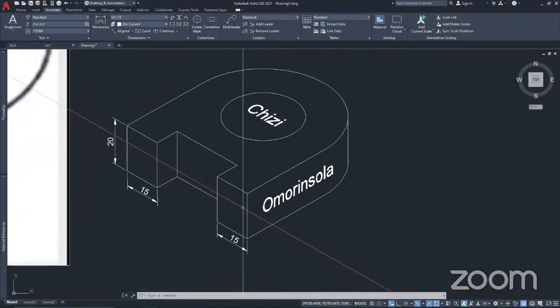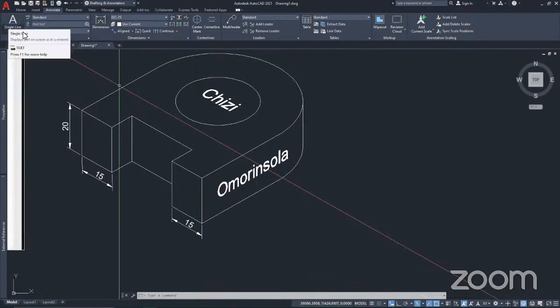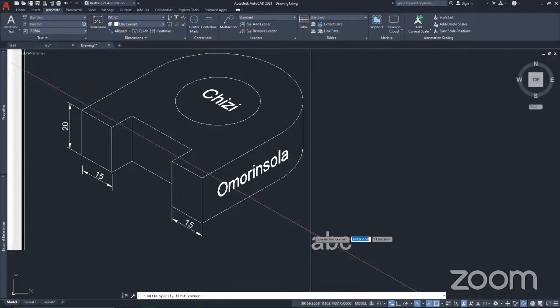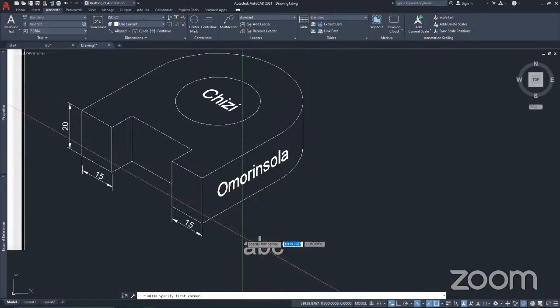Now I want to talk about the multi-line text. Drop this down, go to the multi-line text, and you want to do a multi-line text. Of course, you choose your first corner. In this case, I'll choose this as the first corner. Now, specify opposite corner.